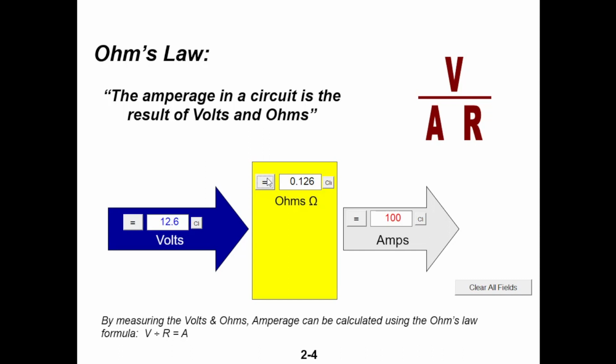Well, what if I had a light bulb? I'm going to clear these out. I don't know how many amps your LEDs draw. I think in the bedroom I've got 4 lights at 3 amps. So 3 amps? No, for an LED? Yeah, no, what is it? I'd say 0.3. I think like a quarter of an amp, let's say, 0.25, right? Then we can see that there's going to be 50 ohms in those light bulbs. So if I applied 12.6 volts to 50 ohms, I would end up with obviously less amperage.